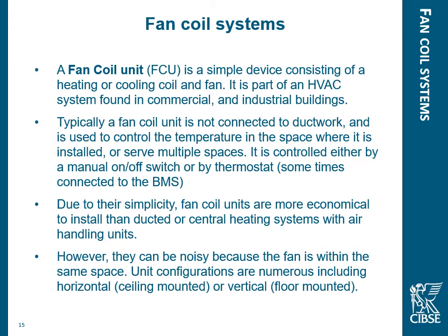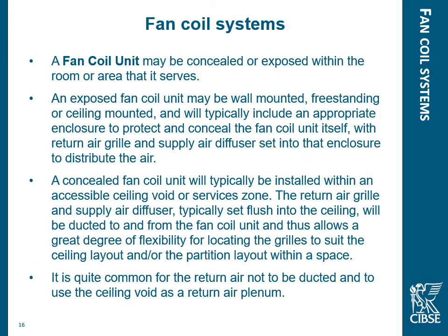However, they can be a little bit noisy, because remember on the VAV system, the fan is actually at the air handling unit. Here we've got a fan in every area. So if the units are not maintained correctly, fans can tend to get a little noisy. Most of the time these units are concealed. They can be exposed, can be wall mounted as well, typically installed within an accessible ceiling.